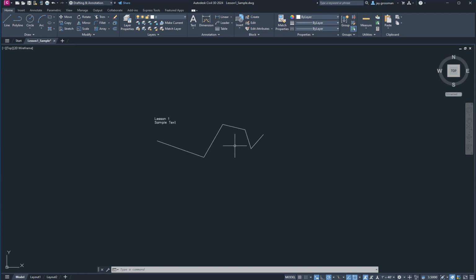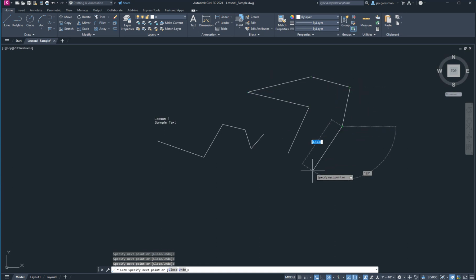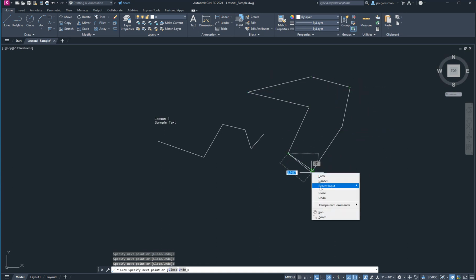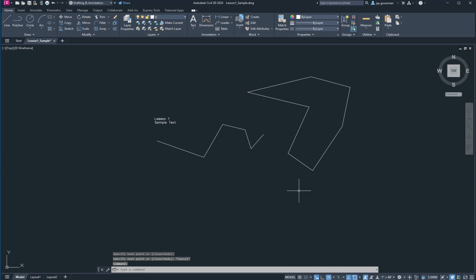If you hit spacebar, now you can see I've got a prompt back up here, and it is ready to start drawing a line again. So it asks you in the instructions here, what does spacebar do? And the spacebar repeats the last command. So that's how AutoCAD is built. It originally started with a bunch of keyboard commands, and it still has those built into it. So spacebar repeats the last command you did. So if you deleted something and hit spacebar again, it'll try to delete something else and move through. So it's whatever you last did, spacebar repeats that.